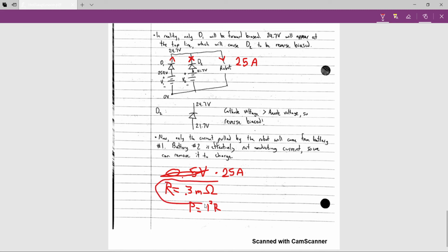So yeah, this should probably be used in that case, this resistance and this current. But basically what I'm getting at, you don't have to remember all these formulas, but having that diode there is dissipating power that currently we are not wasting because we don't have a diode in there. So there is that trade-off, but overall this will let us hot swap, and so it's probably worth it.